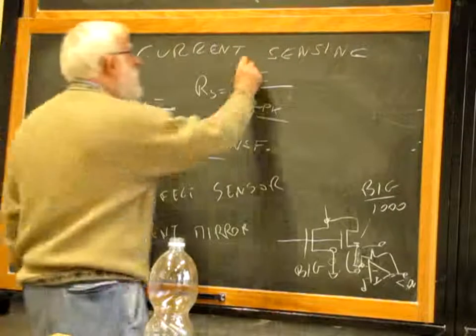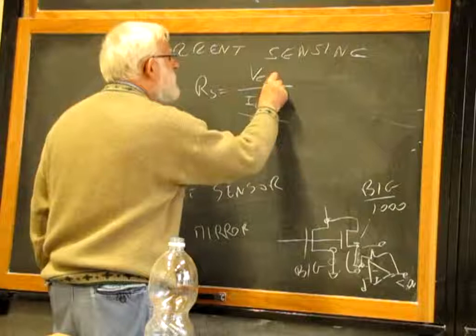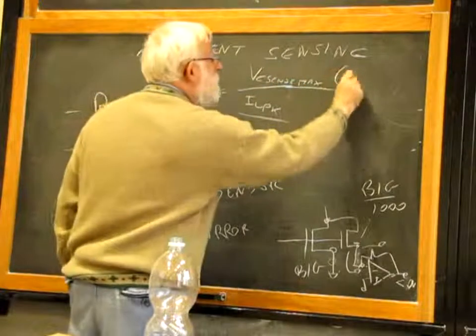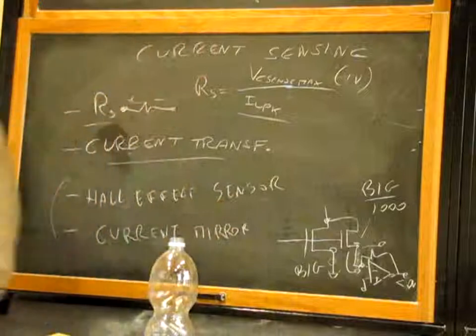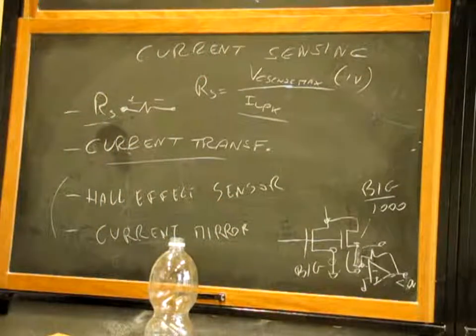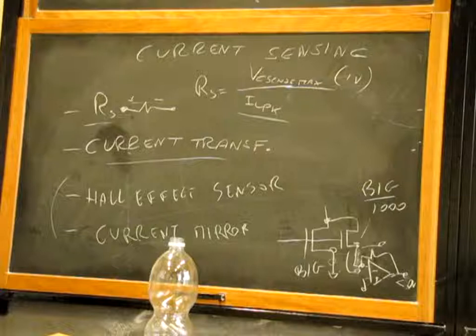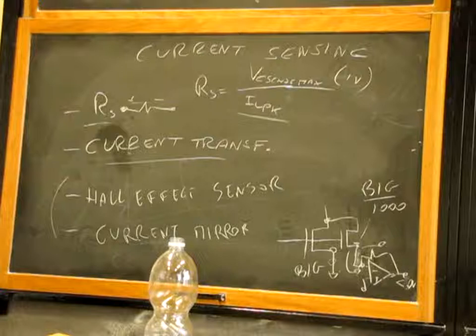So the current sense max is typically around 1 volt. Many ICs, when the input voltage coming from the current sense reaches 1.1 volts, no matter what, shut everything down, because it means something is going bad. So at least they protect the switch.